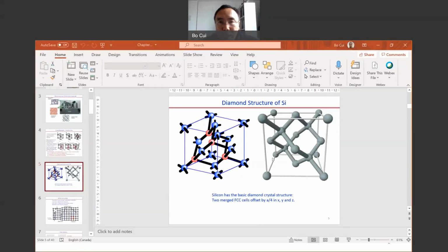Here is the silicon lattice structure. At this level, we have 2 atoms per unit cell, one from the corners, one from the middle. At this height level, we have 2 silicon atoms per unit cell area. At this height level, we also have 2 silicon atoms. At this level, we have half on each face, half of them on each surface, so we also have 2. The same for the other levels. So the number density per area is given by 2 divided by the unit cell area.